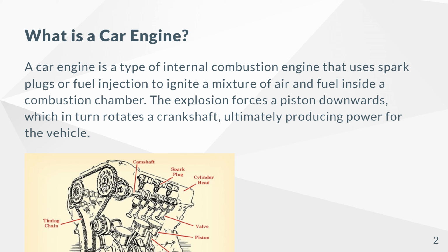to generate that power. The cylinders are where the magic happens, where the air and fuel mixture is ignited to produce power. The pistons move up and down inside these cylinders, driven by explosive force generated by ignition. The connecting rods transfer motion from the piston to the crankshaft, while the camshaft operates the valves that allow air and fuel into the cylinders and exhaust gases out.